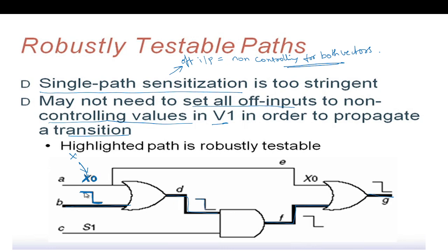And next, now we have got the transition here. To propagate this, the AND gate output 1 should be 1 and the next also should be non-controlling, then only can we propagate this. So this is called steady 1 or strictly 1. So that transition is obtained here. Now for this, if you see it's 1 and 0. This 1 is a controlling value, so anything here will not affect this transition. Now for 0, we need a 0 so that this 0 can be propagated here.